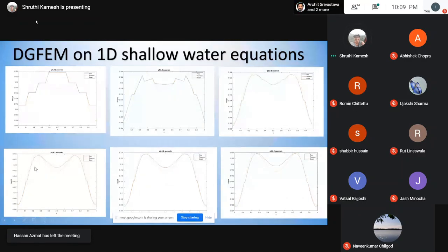discontinuities appear to smooth out, but that's really not the case. But yeah, they're slowly smoothing it out, and at p5, after p2 you don't see much of a change. Which is another exciting thing, that beyond, say, p2 or p3, for most solutions you don't need to go much further, so you save your computational resources that way. Because p3, p4, p5 look essentially the same, except for this particular sink that you see at p equals 5. But those are minor issues, really, and it depends on what you're looking for in a solution.